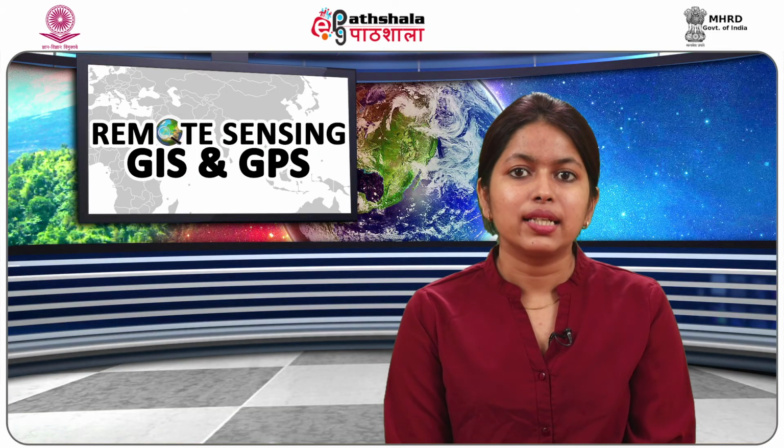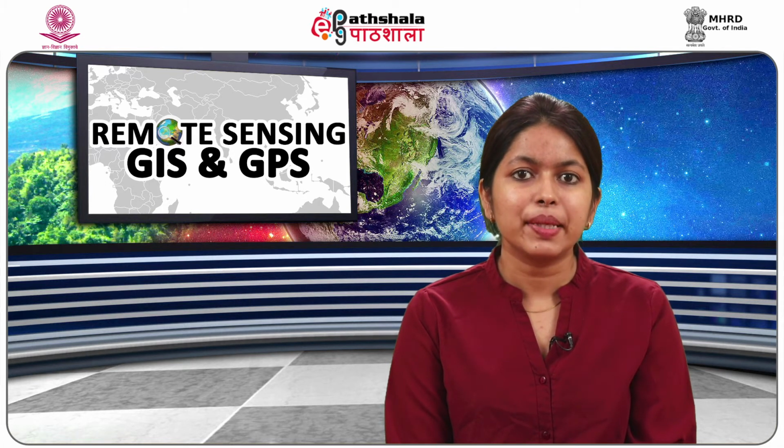Riaño identified, using LIDAR, the tree height, canopy cover, crown base height and the crown bulk density. First, a digital terrain model was generated by differentiating laser pulses with lower height, and these were interpolated using the spline function. Thus, the vegetation height was estimated by removing the ground elevation above sea level.